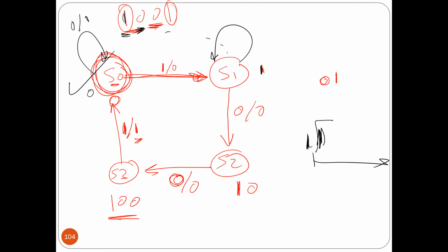That's why I said you have to be very careful, because maybe your circuit or the state diagram is going to work in some cases and may not work in other cases. So think about it. Here I have 1 in hand. I got another 1, so now I have 1 from the sequence. I have to stay here waiting, because maybe I'm going to have 1, 1, and then the sequence will continue.